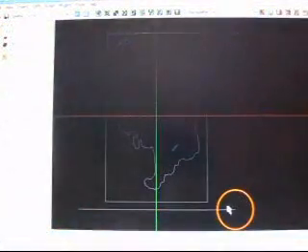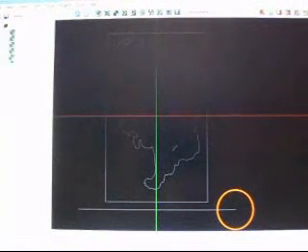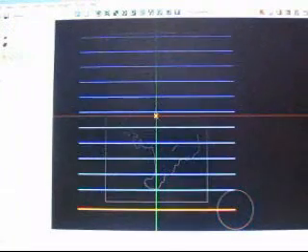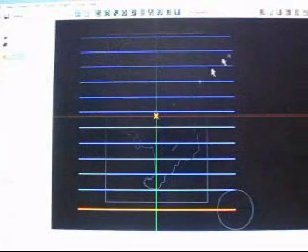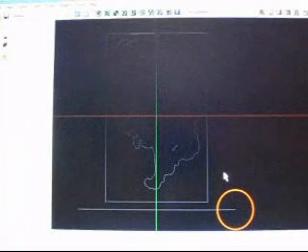The reason why I drew this out for you is because I wanted you to understand the meaning of having this come off the part, because now when you come from your home position to here, you want to make sure that this cutter is off the part, not plunging down into the part. It's very important that you keep that in mind.